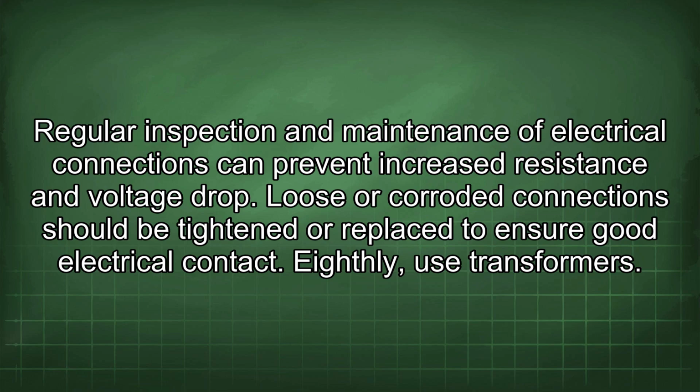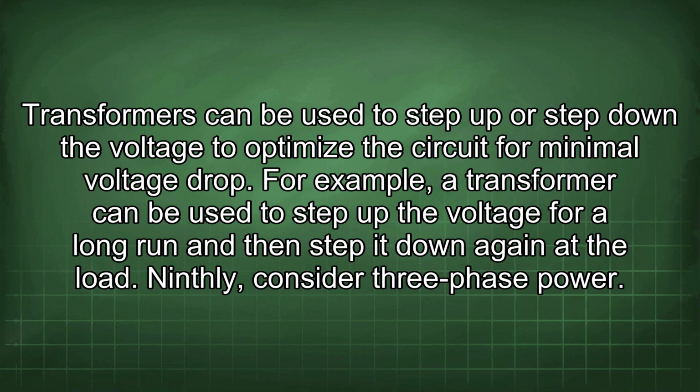Eighthly, use transformers. Transformers can be used to step up or step down the voltage to optimize the circuit for minimal voltage drop. For example, a transformer can be used to step up the voltage for a long run and then step it down again at the load.